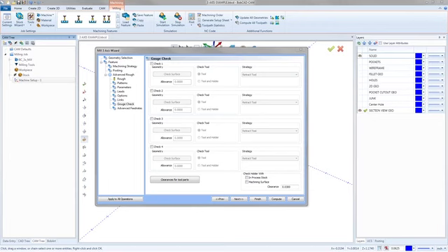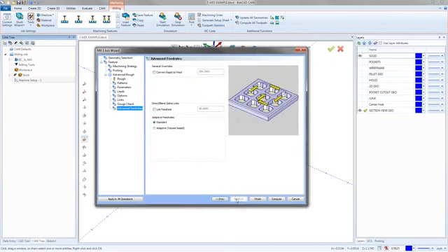If you're watching your simulation and a tool's running into a wall that you don't want it to touch, you could set that wall up or that edge as your gouge check. But if you want a tool to really cut in a specific location, you'll want to set up a boundary. That's pretty much the easiest way to get a tool to cut right where you want. Set up a boundary, and then it will.